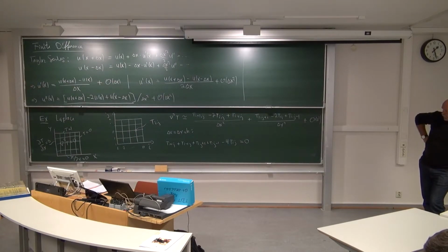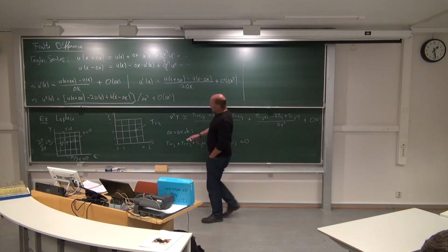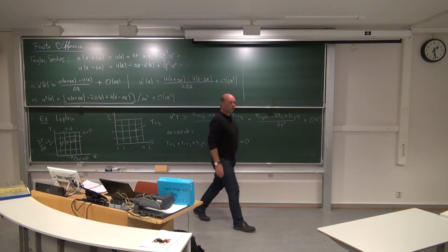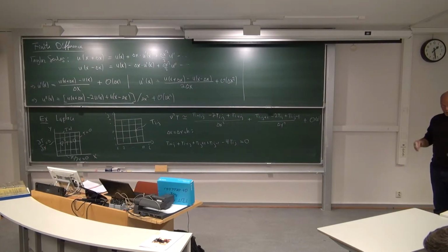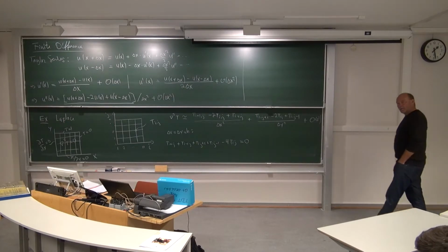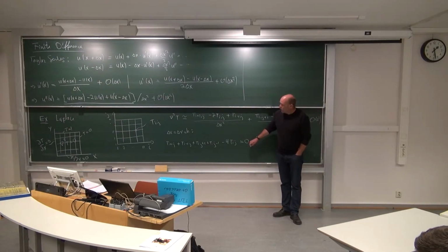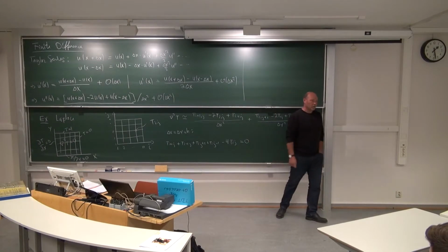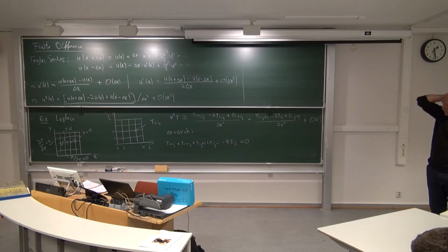So I just need to solve this equation, or these equations you might say, because if it's a 10 by 10 grid you have here, you have 100 algebraic equations which must be solved together. They are of course strongly coupled. So yes, you could set up a matrix and solve it using a direct method, that's possible. But in general, that's expensive. You will blow the memory for any big problems. So no, we are using the modified Newton-Raphson on this problem.